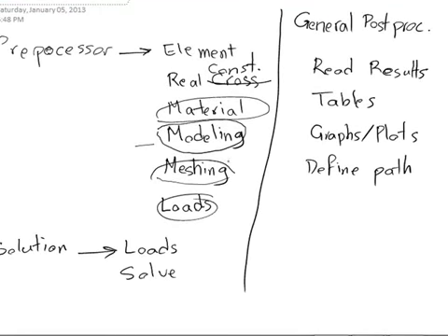I'm just going to be staying on the simple side of the explanation and just tell you that there are nodes and elements that ANSYS needs in order to do the analysis for you. And that's the task of meshing. So when you do modeling and you create areas or volumes or lines, you use the mesh to divide your model into a number of nodes and elements for ANSYS to be able to do the analysis.